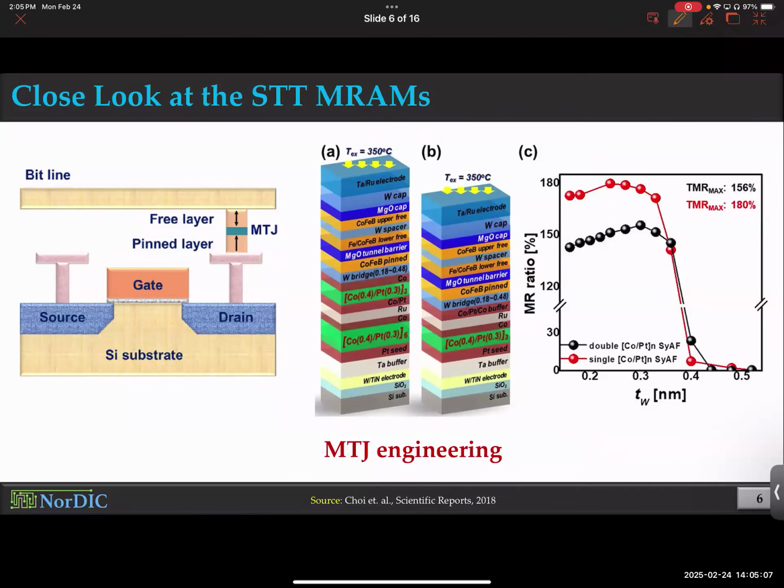So like I said, in our simple model for the MTJ, we had a pinned layer and a free layer, or vice versa, it doesn't matter how you put it. But in practice, you can have multiple layers. Free layer means something with a weaker magnetic field. Pinned layer means something that is really strong as a magnet and difficult to flip. Okay. When you make this sandwich, just imagine, again, another analogy.